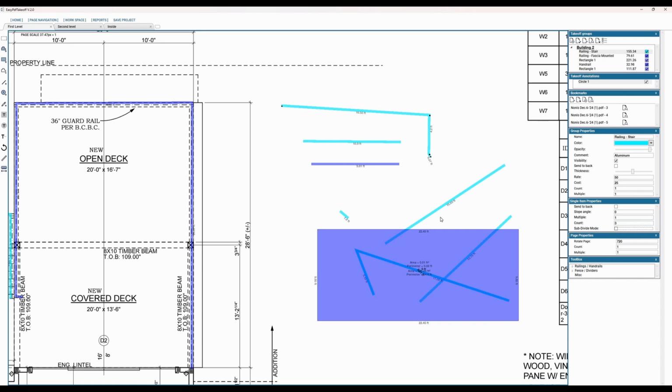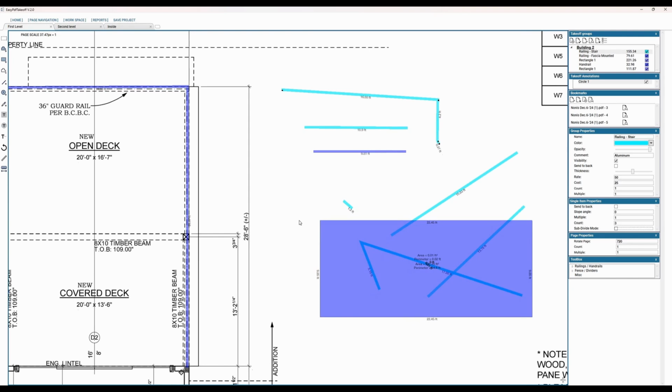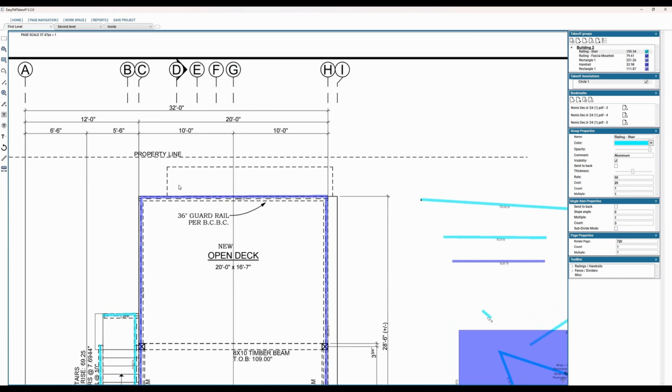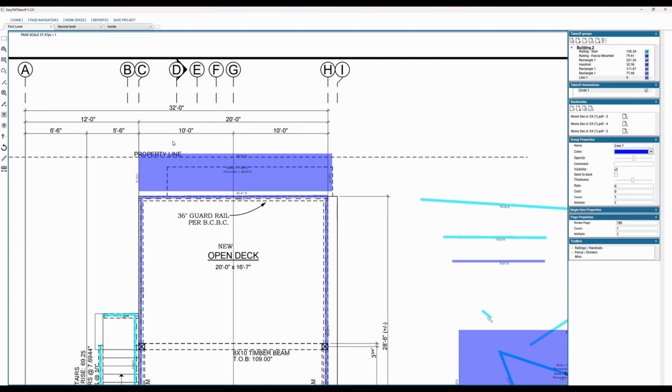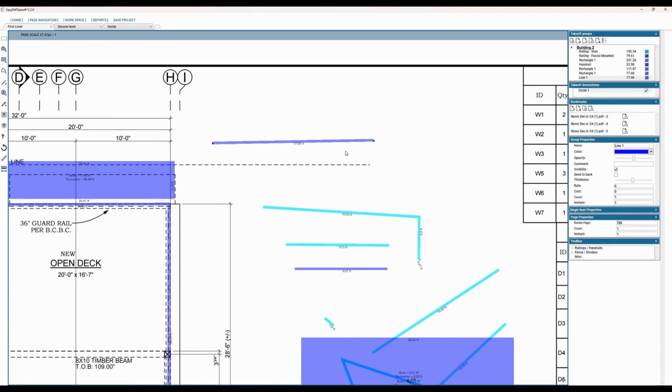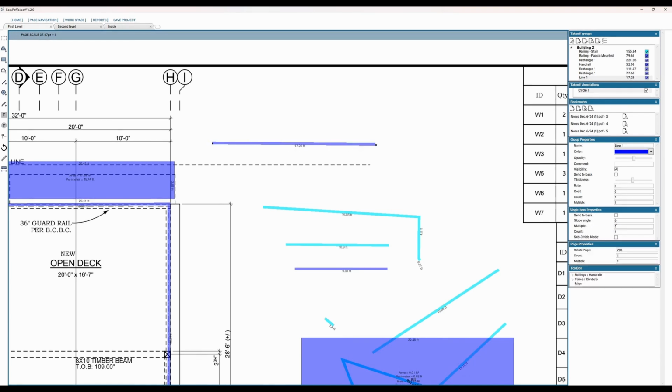There's also a property called a slope angle. One of the reasons you might want to use it is, for example, let's say the ground is uneven. Say you're working on a ramp or a slope, but the property from the top is going to be flat. If you do this one here, you can apply it to the item. Let's say 35 degrees. And this will increase the length of the item to accommodate for a different slope.